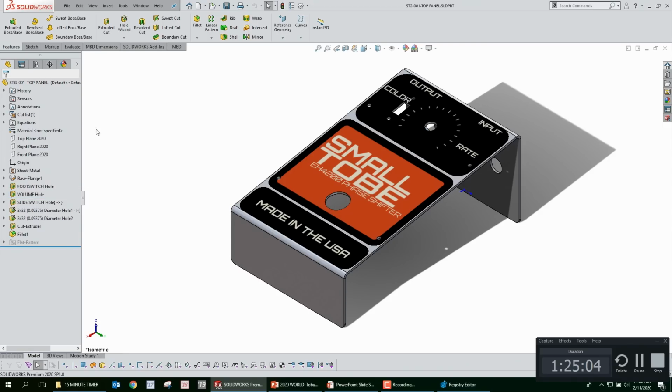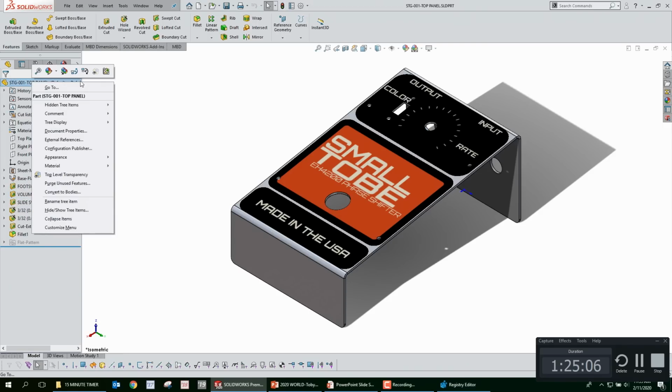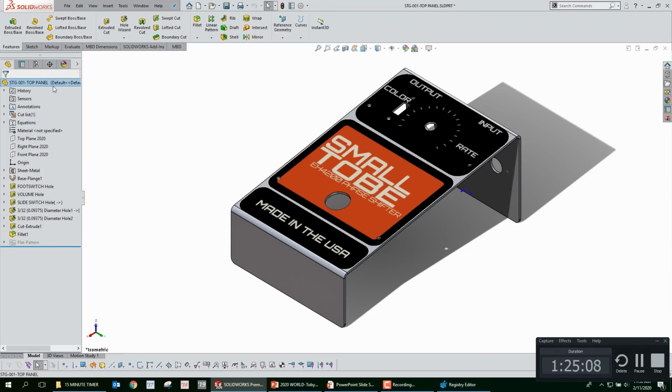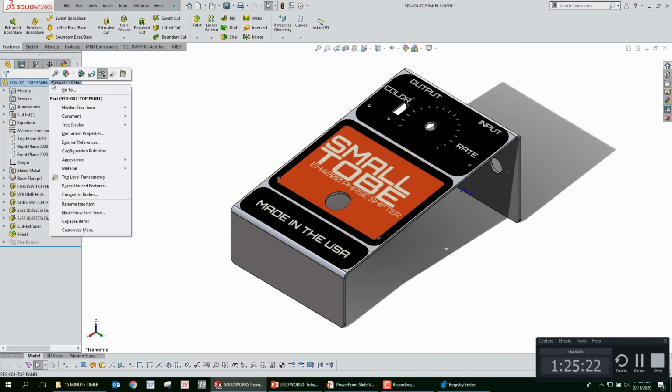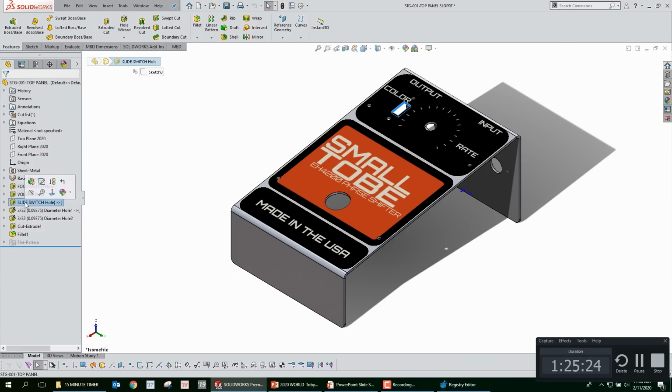They're definitely at the top of the tree. If you right mouse button and you turn on these dynamic highlight references, it makes it harder to rename things. I've definitely seen that. I'll go to rename, and then that'll show up again, and it'll kick me out of the rename function. It is better in 2020, but the two things I would say would be, one, maybe turn these off, and two, just remember you can always use F2 to rename.